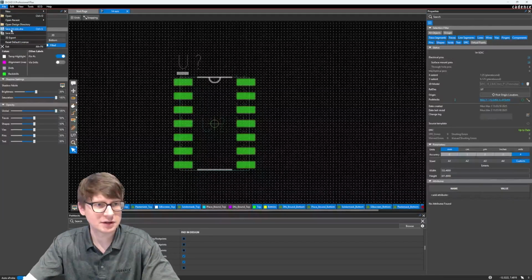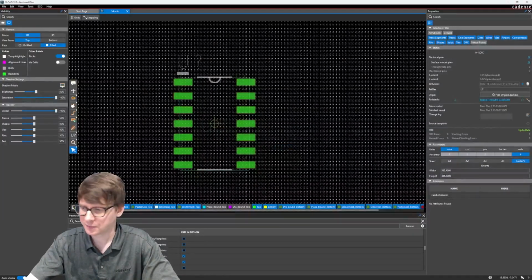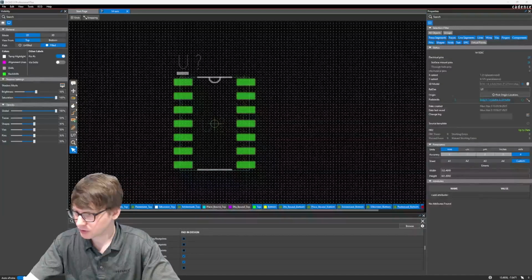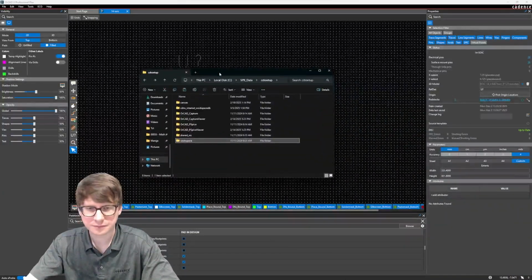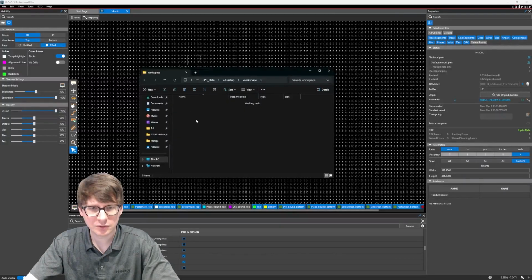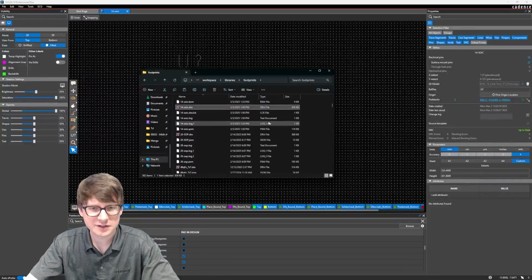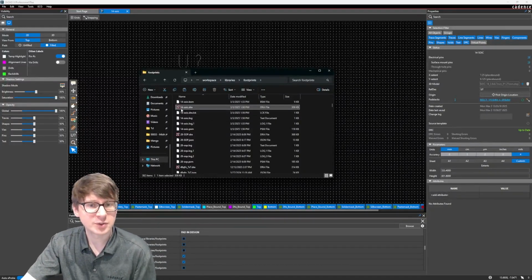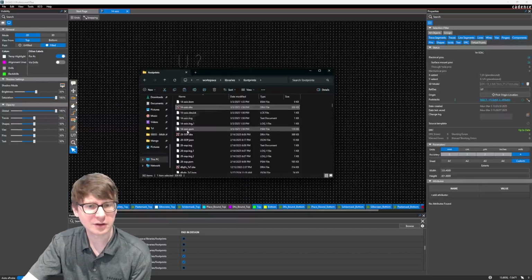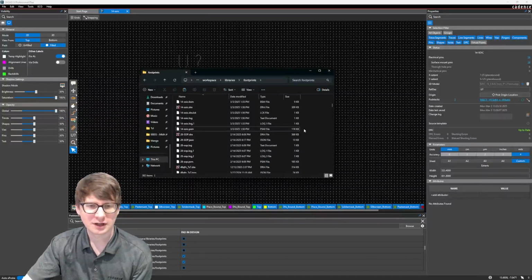So we're going to go ahead and hit File, Save, hit Yes. And one thing I just want to show you guys really quickly is that when you save, let me get to my library here. When you save that, and we'll go into our libraries, footprints, and we're looking for the 14 SOIC. One thing that you should check is make sure that you create the DRA save file, and also you want this PSM file, which is basically just like a packaged or compiled version of the footprint, which is what actually gets used when you place that on your board.